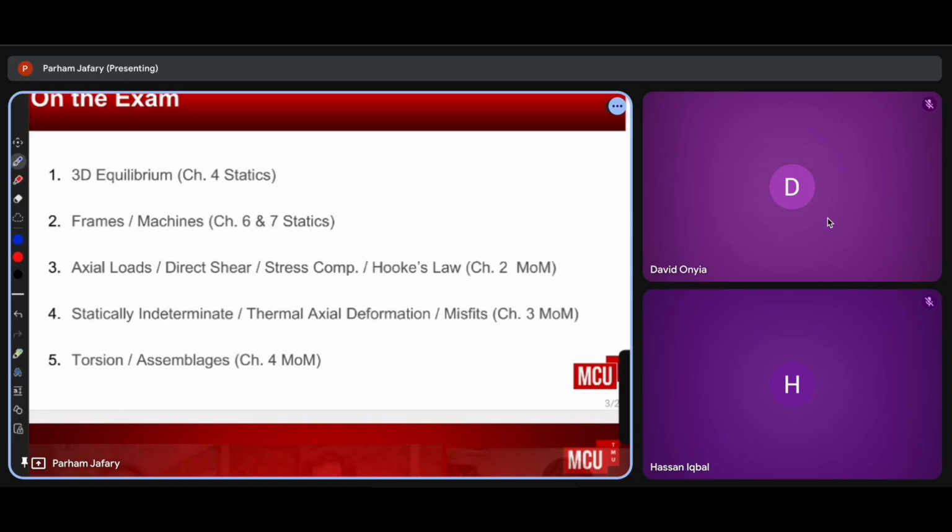What? In the Y direction? Why is that? Yeah, but I have so many unknowns in the Y direction as well, right? So basically, if you want to start with sigma F of Y, you don't know AY, you don't know DY, and you don't know the Y components of TBG and TBH.